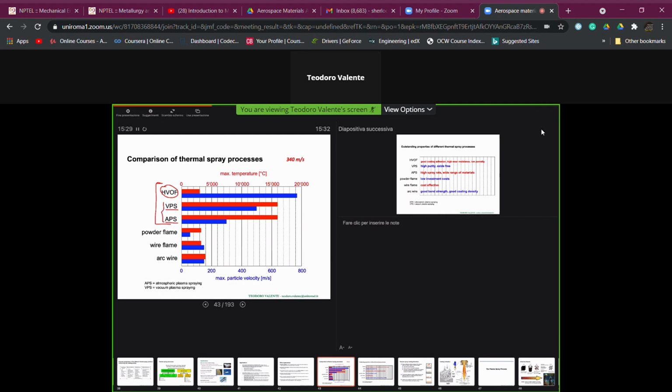And the reason is very simple. One is the cost, but the second one is that we can get good coating quality, because if we are going to spray an oxide-based ceramic and our spraying process is performed in air, we do not care about oxidation phenomena on the starting materials, that is on the starting powders, alumina, titania, or partially stabilized zirconia, because they are oxides.